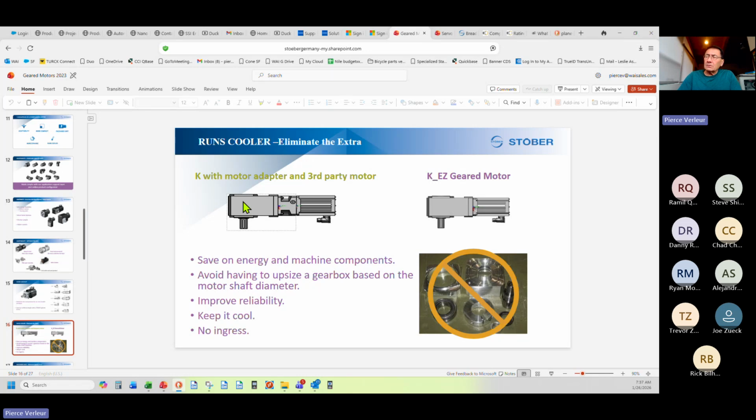How long should a servo gearbox last? In my experience, assuming you've rated everything correctly, the motor should last 5 years under continuous operation. If it's intermittent operation, you're going to extend the life a little bit.